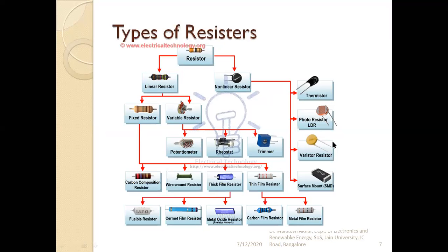Once we get the information in digital form, we can give it to the processor to check whether the value is more than 25 degrees centigrade, or less than 35 degrees centigrade. Depending on that, we give instructions in the program, and it checks the predetermined values and takes an action to switch the AC or the fan on or off. Those AC and fans should be connected to the controller through the relay system.